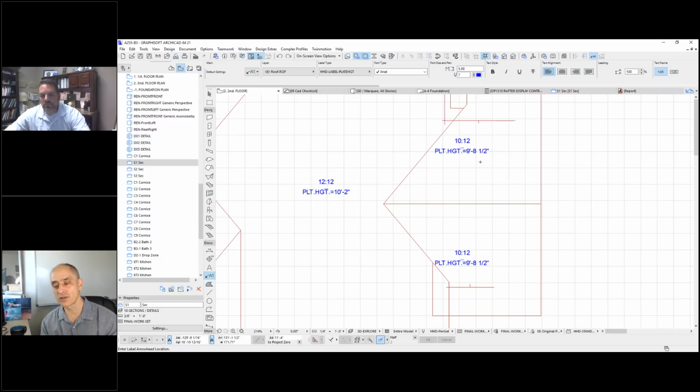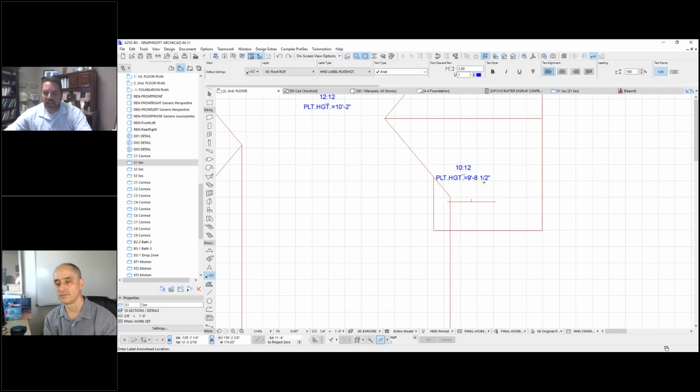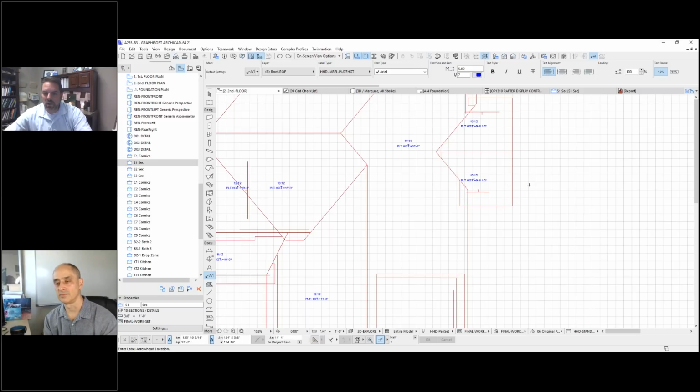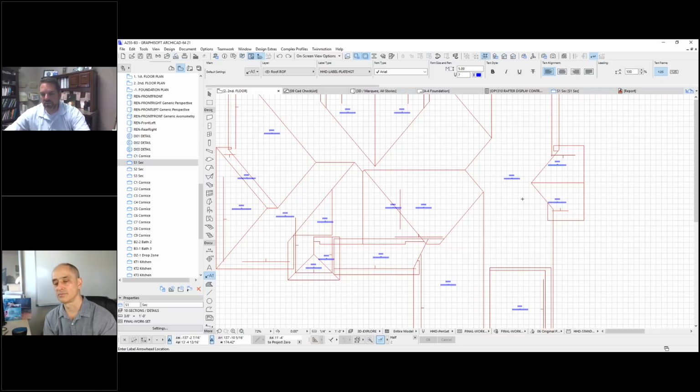How do you approach your fascia and soffits and things like that? Once we design, we commonly go 9, 8.5, which allows the plate to be placed on top of the common ceiling joist at 5.5 inches, and then we base that rafter off the top of that point. So it picks the rafter tails up, because a lot of our windows we'll header out at 8 foot on a 9 foot ceiling. But if you've got a 10-inch pitch, then your eaves are going to be killing into the top of the windows.